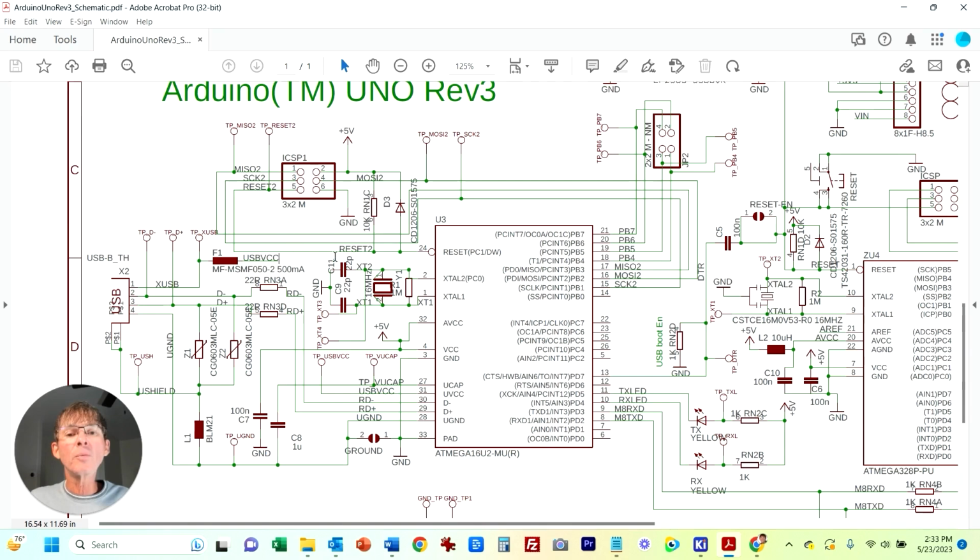Then let's see the reset. This resets only through the microcontroller programming interface, is how you'll reset this microcontroller. This microcontroller over here that runs your sketch does a power on reset, and you can also reset it with just a manual switch.